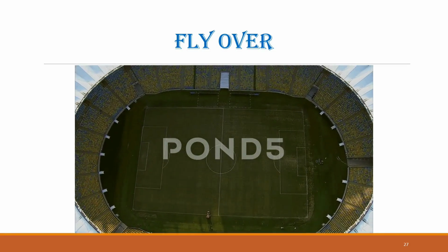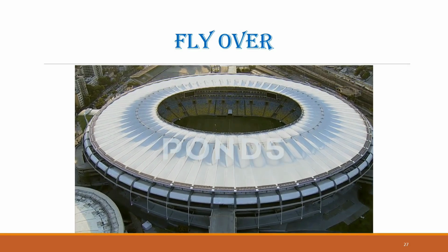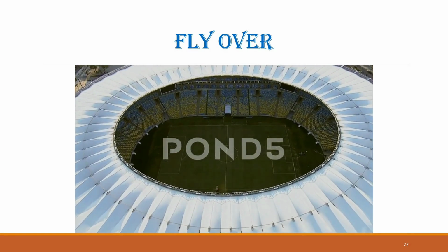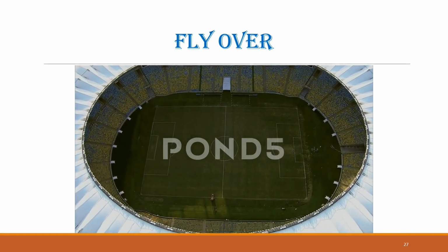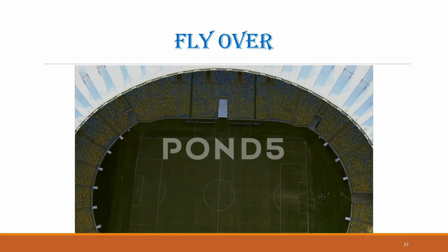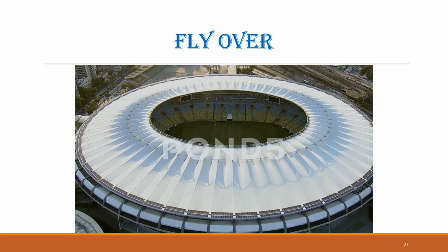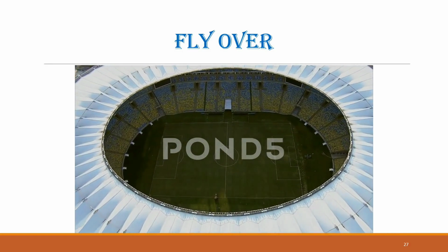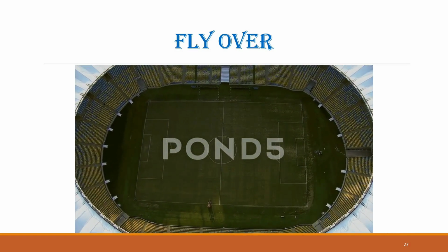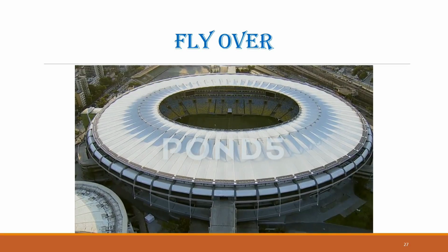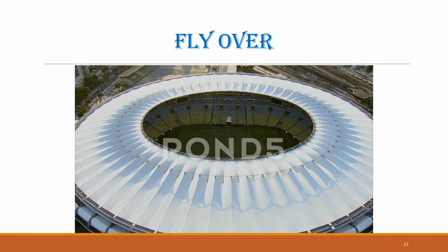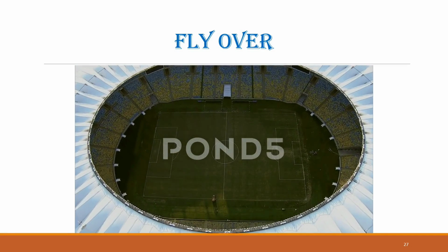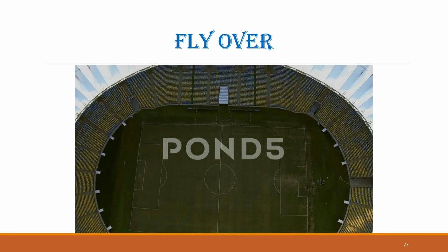From a practical standpoint, capturing a good flyover shot requires smooth forward flight and careful framing of the subject. The drone should maintain a steady speed to ensure the motion feels controlled, rather than rushed or unstable. The camera angle is usually adjusted to keep the subject in view as long as possible, allowing the viewer to clearly recognize it before the drone passes over it completely. When executed properly, the flyover shot becomes a powerful storytelling tool that combines motion, perspective, and scale.